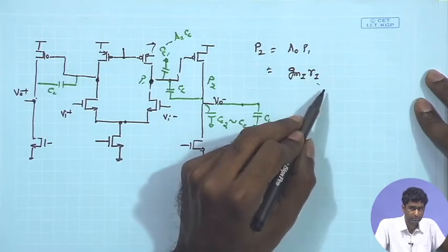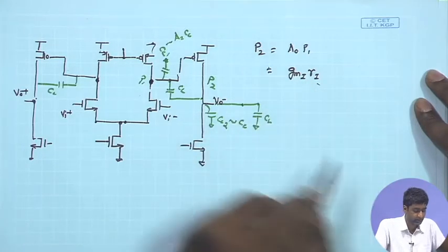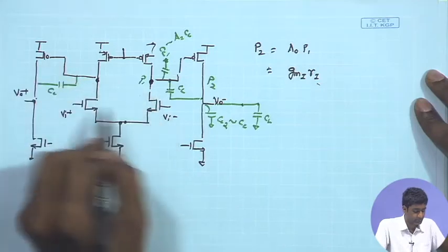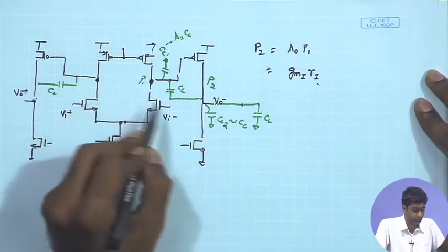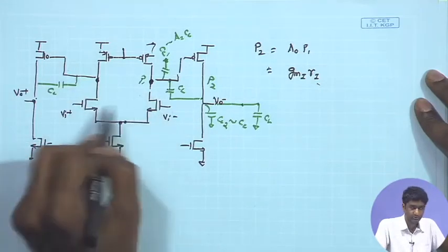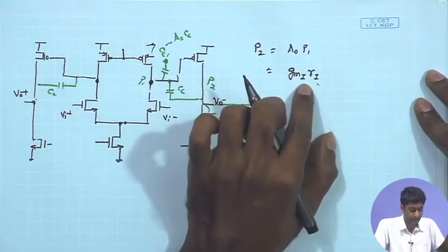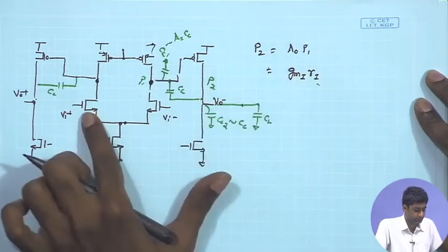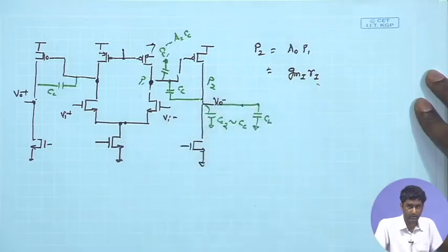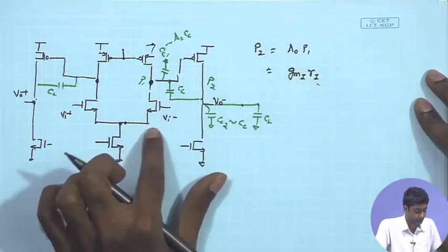and that is what I am mentioning as R1, that is the small signal output resistance of the first stage effectively, and GM1 is the transconductance of the first stage. So, GM1 corresponds to the transconductance of the input pair. So, here the subscript denotes the stage, the first stage GM1 R1, and then you have the second stage, the